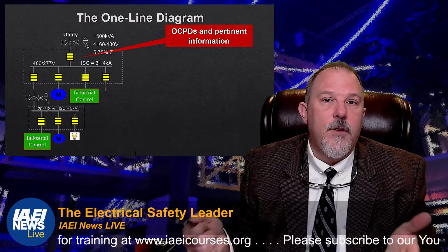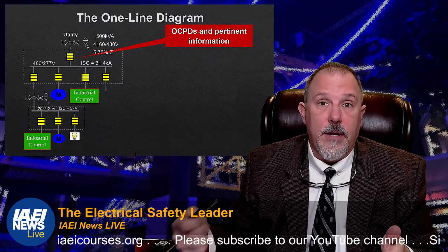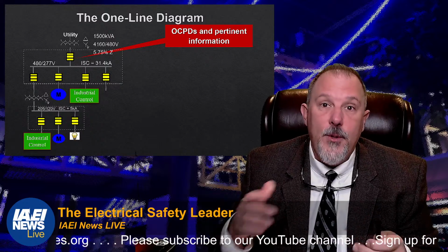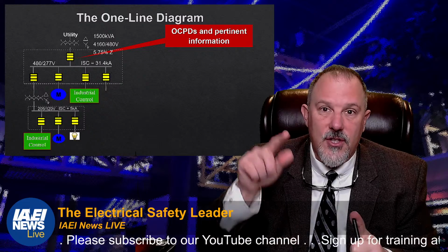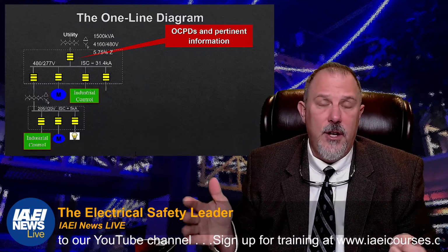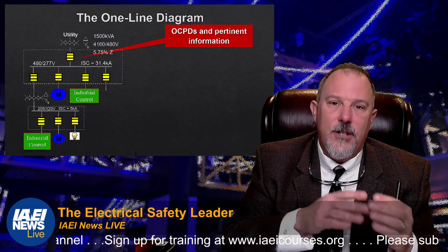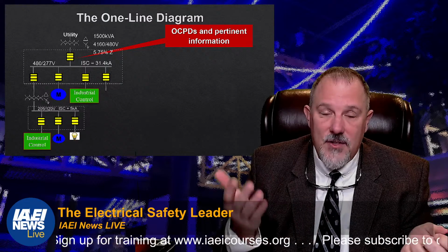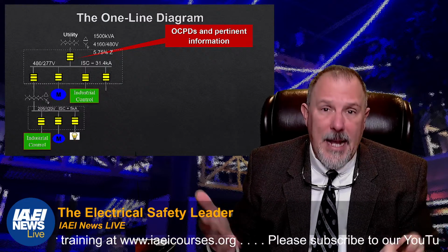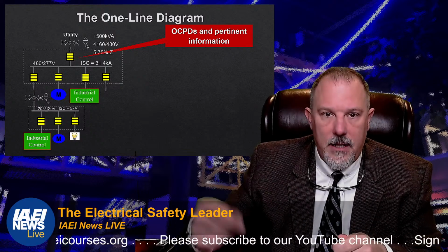I can put ground fault protection of equipment anywhere I want to, but you need to tell whoever it is, and you'll do that on the one-line diagram. Maybe you want arc reduction technology on there, so you'll say AF or some other designator. In most cases, there's no standards. There are some standard nomenclatures that we'll use, but I've seen engineers get creative in saying this is what I want here, because they want to make sure that they get the right quotes.